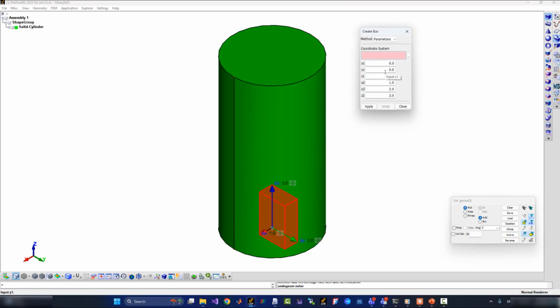So I have to give x1, y1, z1 coordinates for the first corner point, then x2, y2, z2 coordinates for the point opposite diagonally. Now again, x1 and y1 should be both equal to -4.5 inches. z1, the lowest z value basically, I should set equal to -2 inches so that the bottom face of my box-shaped solid plate is 2 inches below the bottom face of the cylinder.